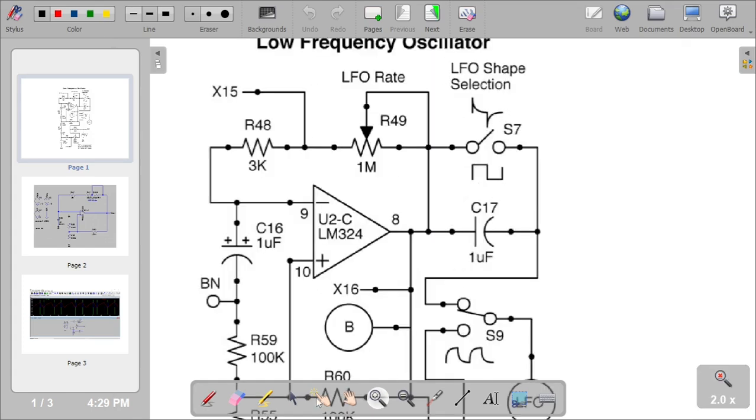Okay, so this is a bit bigger. So this is your square wave, and if you differentiate this thing, here you get 0, so that would be this part. Here you get 0, that would be that part. And for those edges which have a very high slope, basically, you get those spikes. So you get one spike here corresponding to that edge here, another spike going the other way for this edge, and then there would be another spike here. I don't know how this thing sounds, but there must be a reason why it's there.